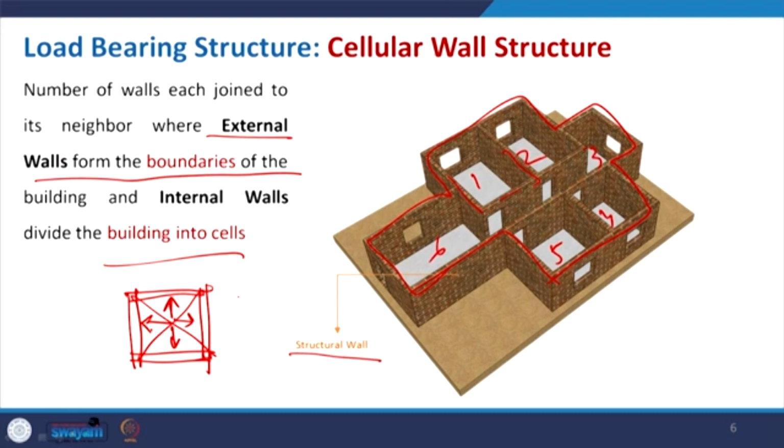Okay, but the moment instead of a square one, if you get something like a rectangular one, then the distribution will change. So basically in that case the maximum load will go to the longer side, and accordingly the minimal will go to the shorter side. So, depending on the wall position and direction, the load will also transfer accordingly, if all the other parameters, the homogeneity, the thickness of the wall, all the sides remain the same.